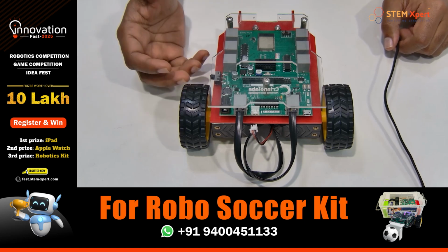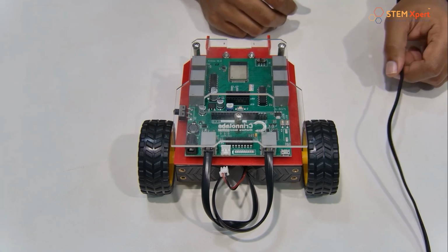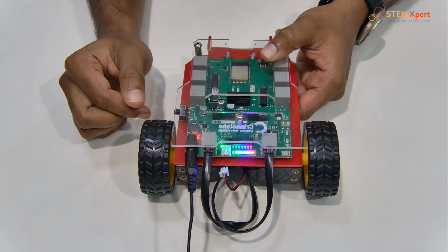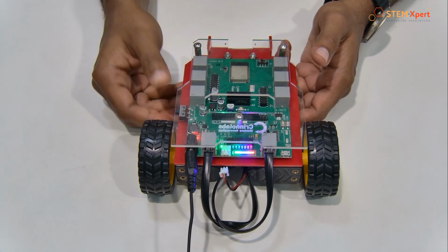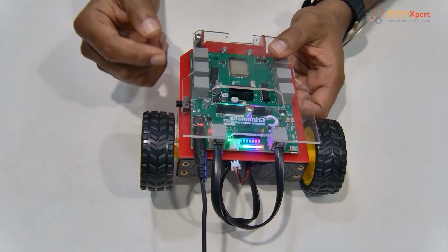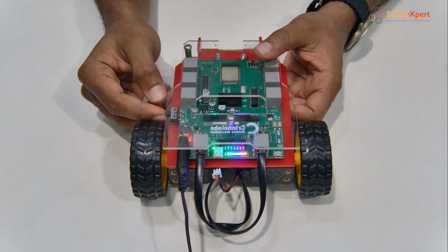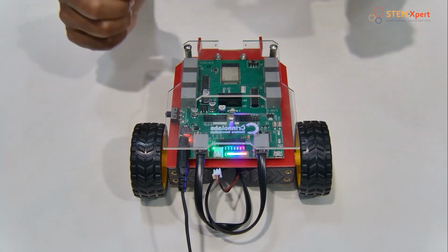As you can see here, this is our robot, and there you can find a DC jack which is used for connecting the power adapter. So let's connect the power adapter to this point. You have to plug in this one, and there you can find this board is now powered up. Once it is getting enough energy, the board is ready, and here we should turn on this slide switch to make the Kreno board work. If you want to upload the code, you have to turn on the switch. And in the next part, we are going to connect the USB cable with our robot.